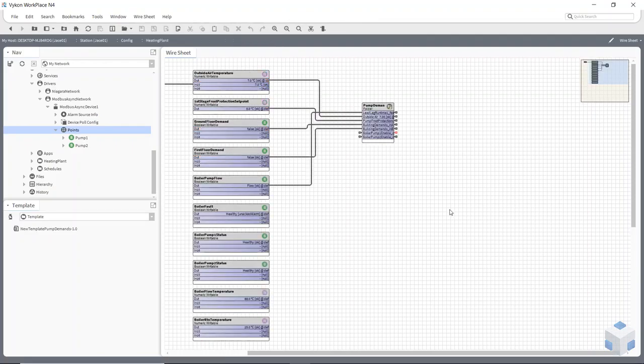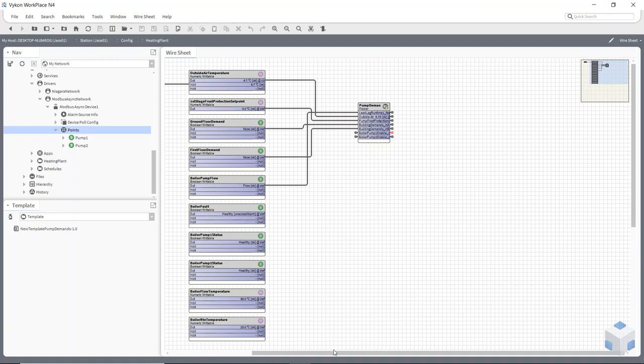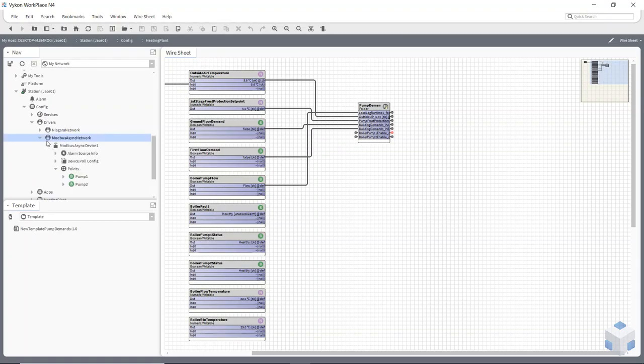But you can see how, once you've made templates, you can make templates of anything, more or less. You can make templates of a Modbus register, for a meter or something like that, which might even have a graphic on it. So templates are really useful. You build up a library of templates, and what you'll find if you do make a template underneath Modbus or underneath BACnet or whatever, they will only work in that space.